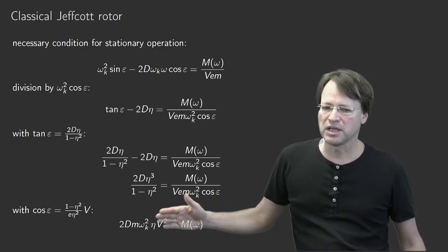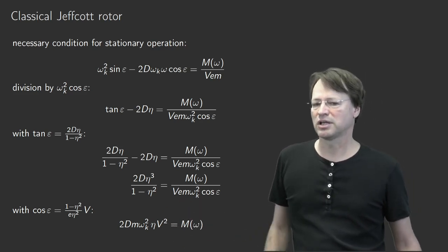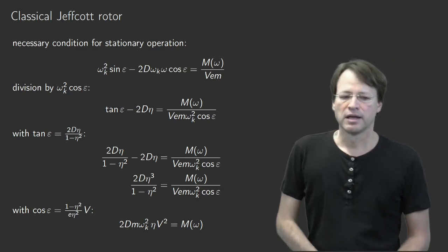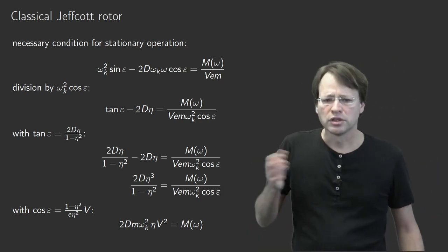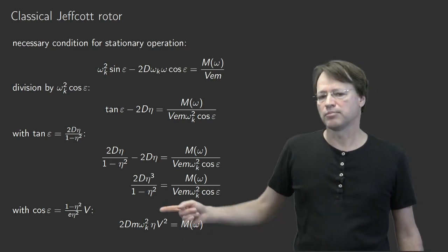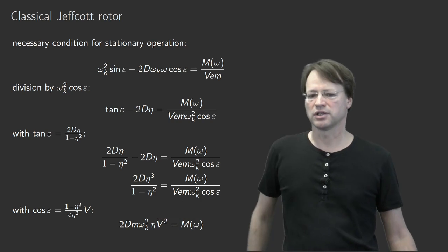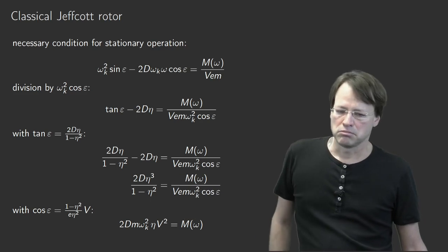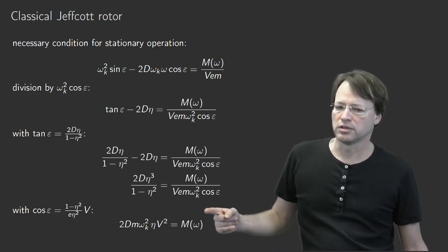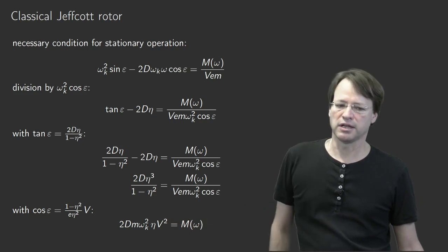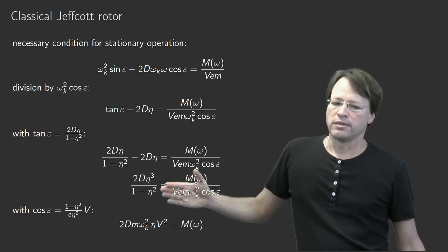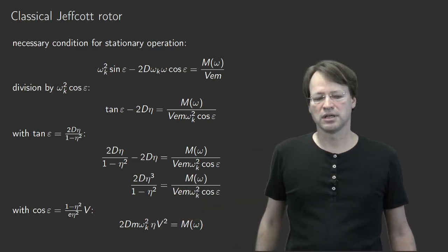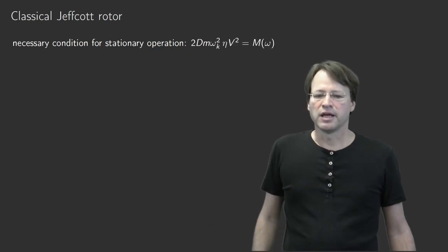That equation will not be as short as represented here. It's nice, but we have to insert the result for the magnification factor v here. And for just drawing this diagram you can use, for example, MATLAB, and you can use that expression in this form. So what you do is you change eta, or the rotational speed omega, keeping omega k at a certain constant, and then you can draw that system characteristic. So you fix all these constants here, and then you can draw this curve. It will look as follows.